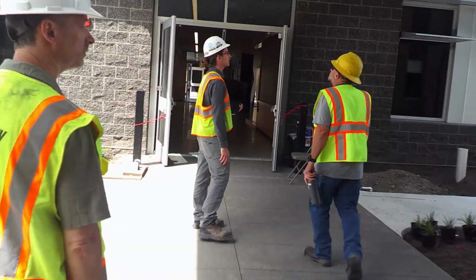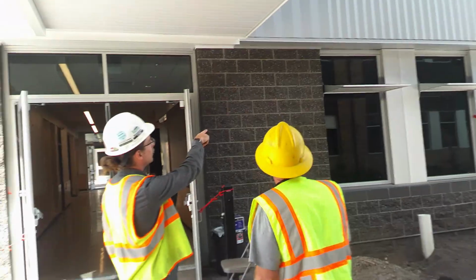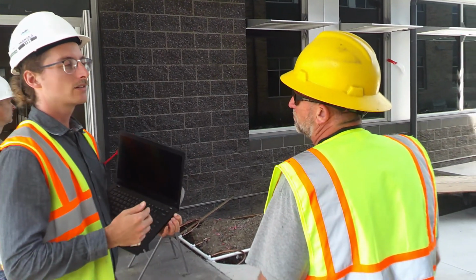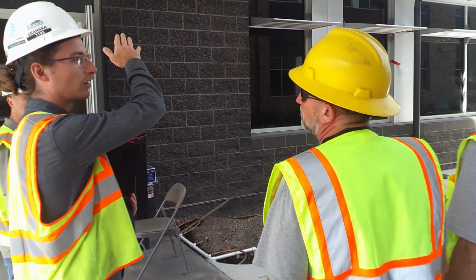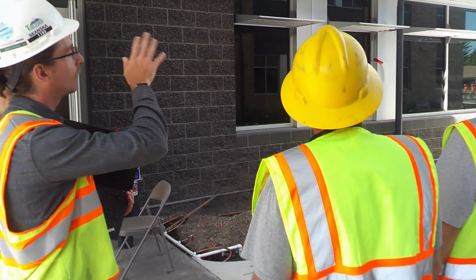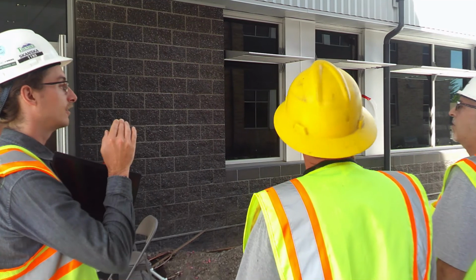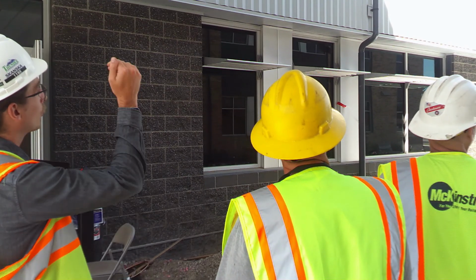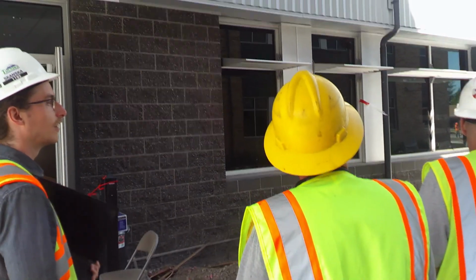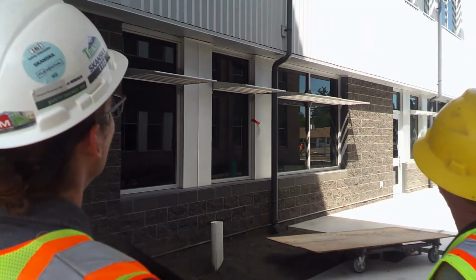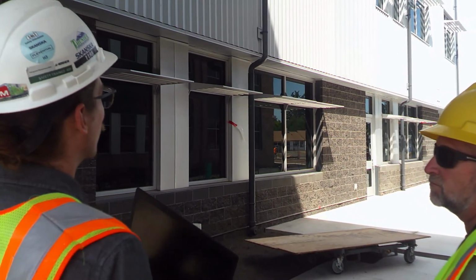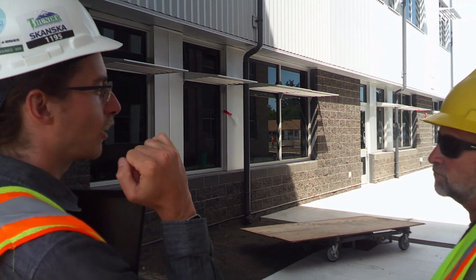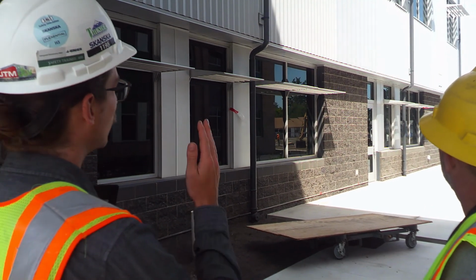Just another little piece of info. A lot of the classrooms have these little awning things. I've found that on these sunny days, they will reflect a ton of light into the photocell. So I've had those calibrations set pretty high. You need a lot of light hitting that photocell for it to start dimming them down, because the photocell will be getting a lot of light, but there's not actually a lot of light lighting up the classroom. It actually came up on one of the commissioning checklists that they thought the lights weren't dimming, but they just probably didn't use a strong enough flashlight on there because it's set so high.